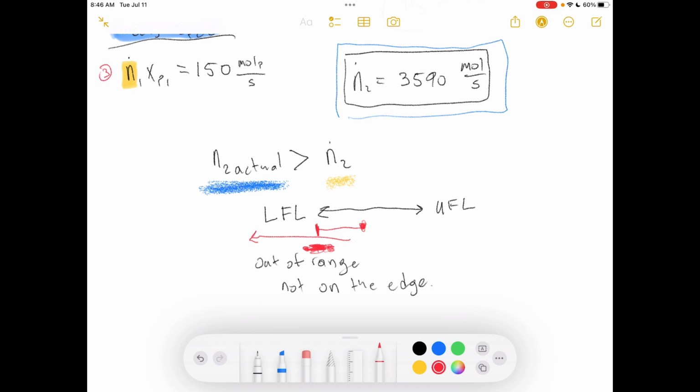So in reality, if your flow rate is variable within this range, you want to go well past that range. Not too far, because you're paying for this extra air that you're pumping into the stream. So you want to go far enough that you're safe, that you're not going to be sputtering, but not so far that it's a heavy cost burden. So you want to go away from this limit edge. Okay, well, that is it for part C and for problem 4.11.